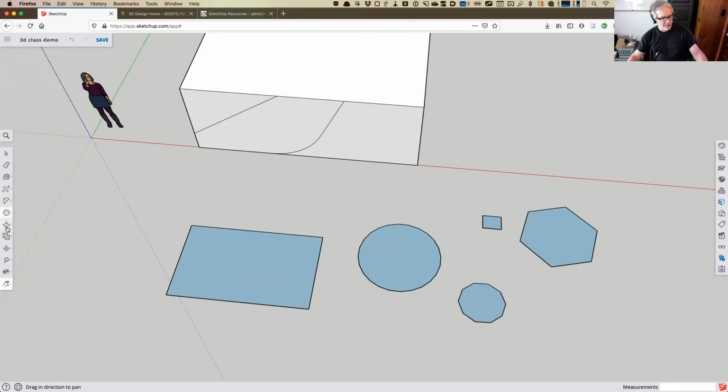All right, now we're going to get into a little more 3D stuff, complexity. And that is these push tools, I like to call them. So we have 3 tools nested under here that are kind of related to this pushing operation. And that is push pull, follow me, and offset. Push pull allows you to take a shape, closed shape, and modify that shape into a form.